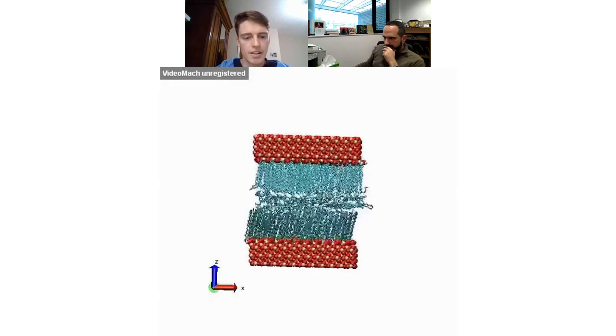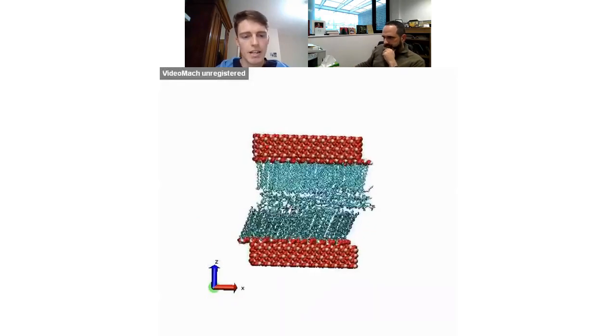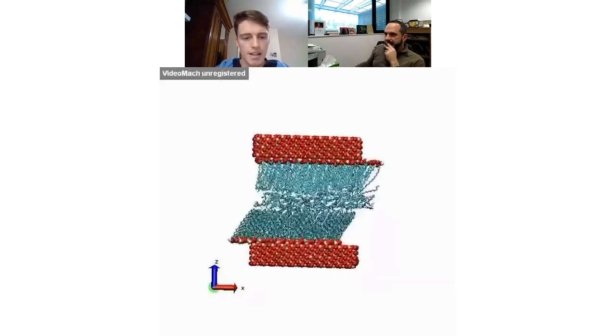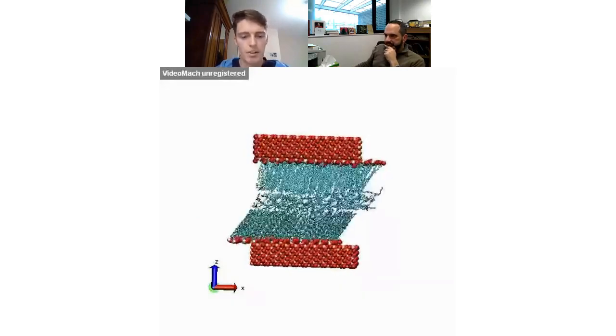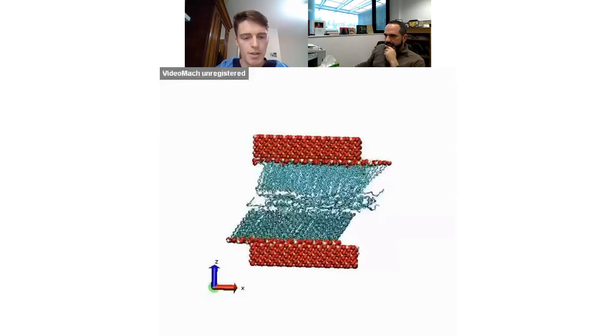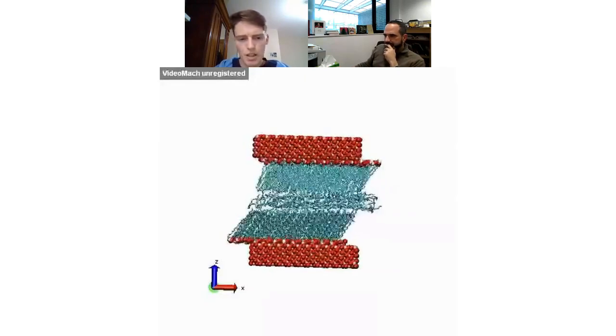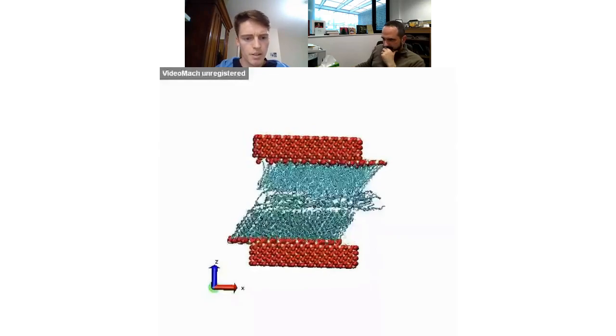And here you can see, on the other hand, that you've got very clear solid-like friction modifier layers. You can see that there's clear slip between the bottom of the friction modifiers and the lubricant there in the middle, and that's the case that gives much lower friction. And if you could just go on to the next slide, please. Yeah, and the next one.